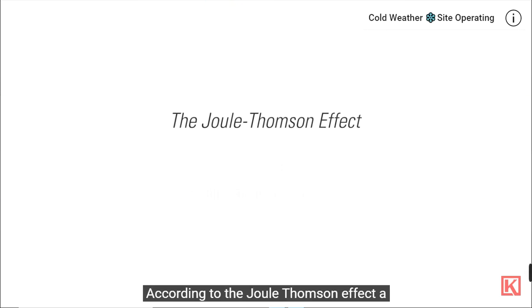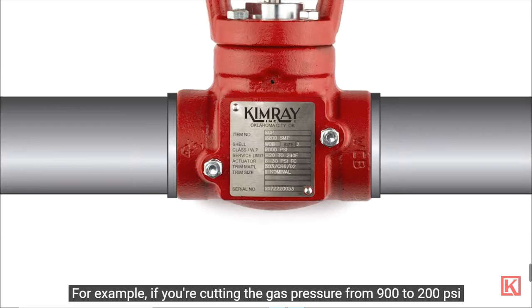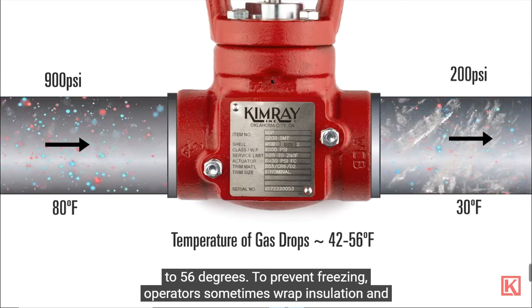According to the Joule-Thomson effect, a 100 psi pressure drop results in a temperature drop of 6 to 8 degrees Fahrenheit. For example, if you're cutting the gas pressure from 900 to 200 psi across a control valve, the temperature of the gas would drop approximately 42 to 56 degrees.